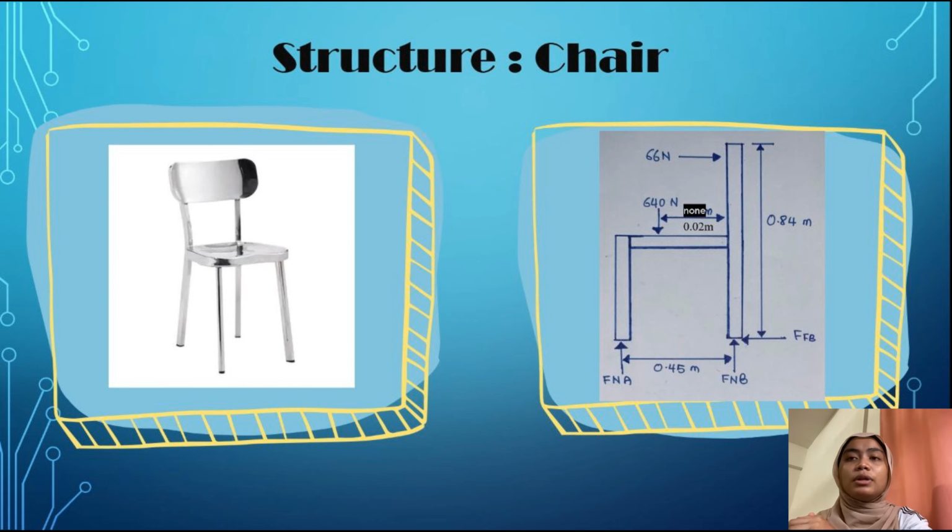Okay, so for now, I will explain about our chosen structure. This is our chosen structure, which is a chair. This is our chair using stainless steel, and beside the photo of the chair, that is our idealized model. As we can see in the idealized picture, we have the measurements: the height of the chair is 0.84 meter, the force is 640 Newton, and the distance 0.02 meter, and we have FNA and FNB, and the distance between FNA and FNB is 0.45 meter. After this, my friends will explain more about the equation.